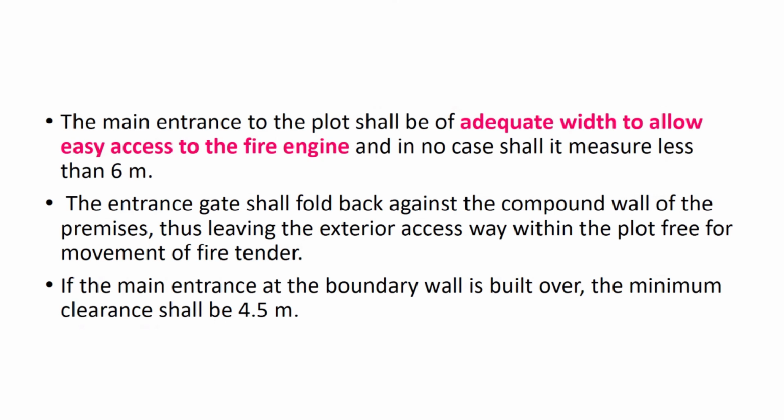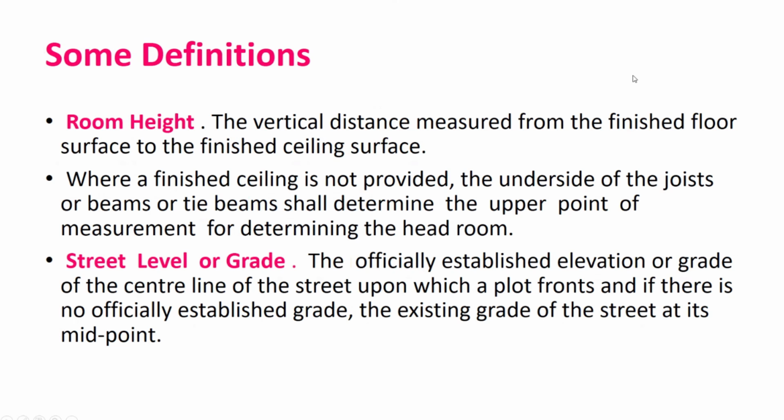For multi-story buildings and structures of height more than 50 meters, it's a huge, what you call as a high-rise building, more than 50 meters height, minimum 3 boreholes at each building or the structure. हर बिल्डिंग के ऊपर में 3 बोरहोल लेना पड़ेगा.